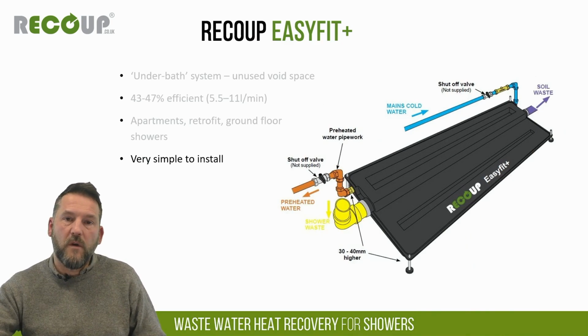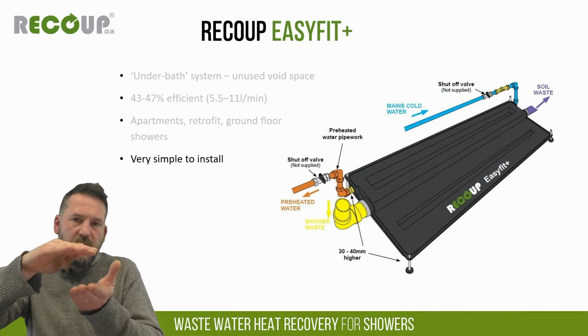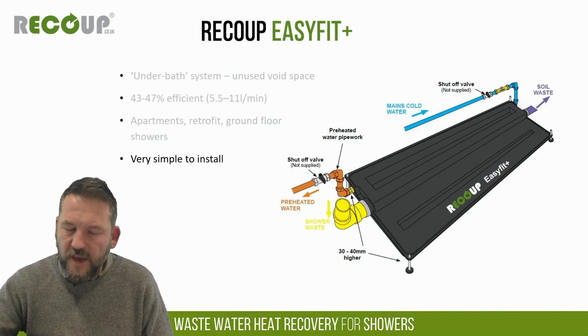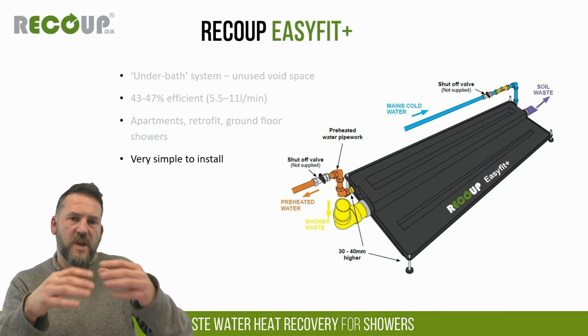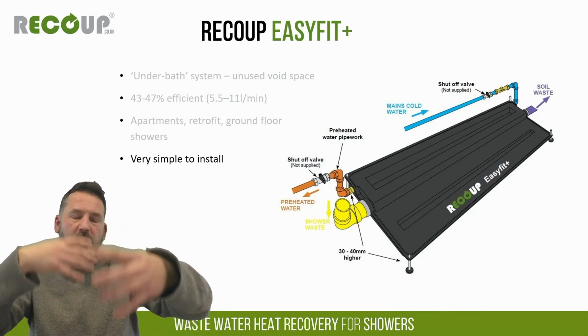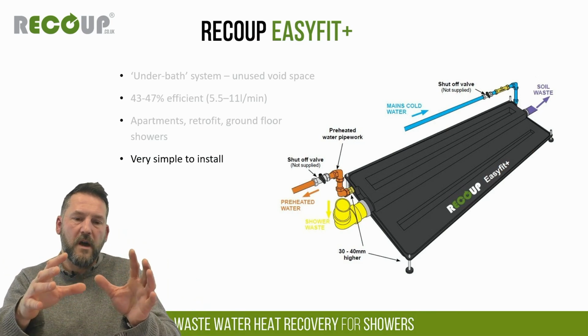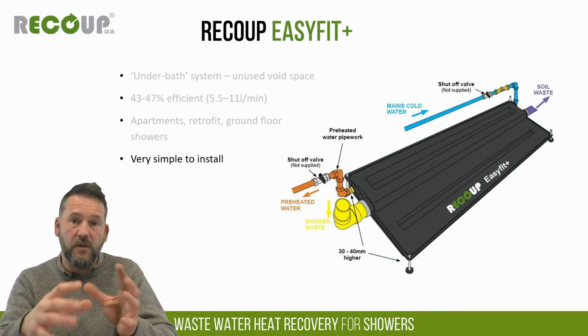And as I said, it works in the same basic way. We've got warm waste coming in one side of the heat exchanger, going out the other side, counterflow heat exchange, so the cold water comes in one side. In this case, we have a flat serpentine exchanger that goes all the way through. It's about 2mm above the base of the unit. The warm waste from the shower or bath will flow through the unit and mix and turbulate over the exchanger, which causes lots of mixing and therefore lots of heat exchange.